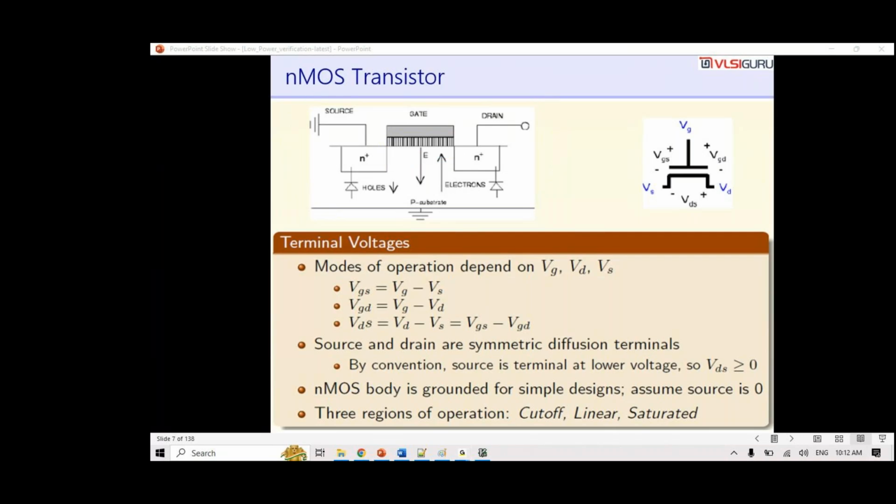As it reduces, the amount of voltage you need to apply to form a channel here won't be high, right? It'll also reduce because you are reducing the oxide width. But then it leads to unwanted effects, where something called quantum mechanical tunneling comes into the picture, and that leads to increased impact of the leakage currents.